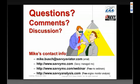Okay, here's a specific one from Douglas. What leaning technique can you suggest for a turbocharged B36TC Bonanza? Well, gee, exactly what we were talking about. Again, with a B36TC, the engine is very, very similar to the engines in my twin Cessna. They're TSIO-520s with an automatically controlled wastegate. And the specific leaning procedure that I use, which would be totally applicable to that Bonanza, is reviewed in the latter part of my Leaning Basics webinar, which you can get off the EAA video server. That would probably be the best starting point. But your airplane's engine is almost identical to the ones in my airplane, and so the leaning procedure would be pretty much identical.